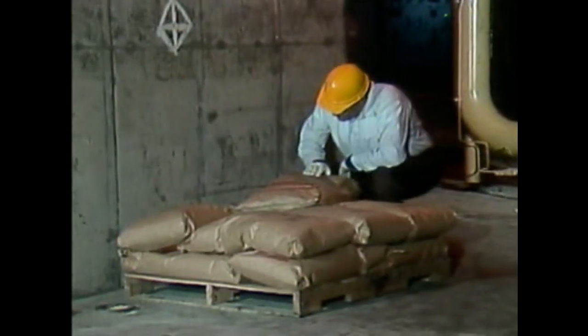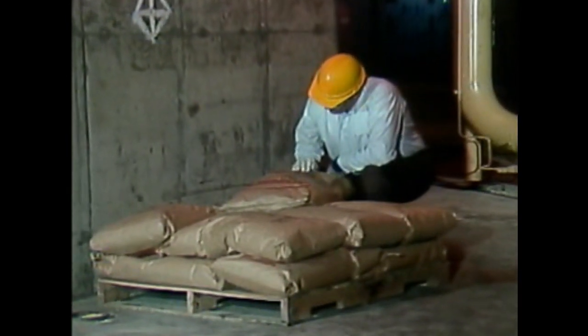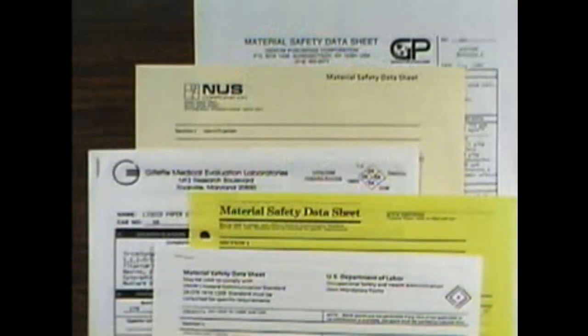Many of the chemicals used in water treatment can be hazardous if they're not handled properly. You need to be aware of the specific dangers associated with the chemicals you work with and know how to protect yourself from them. Before you handle any kind of chemical, read the information on the label or its material safety data sheet, and, if necessary, ask a supervisor about it.